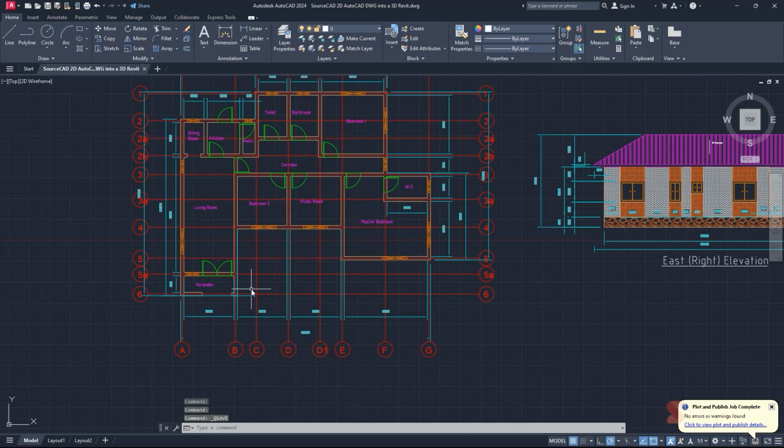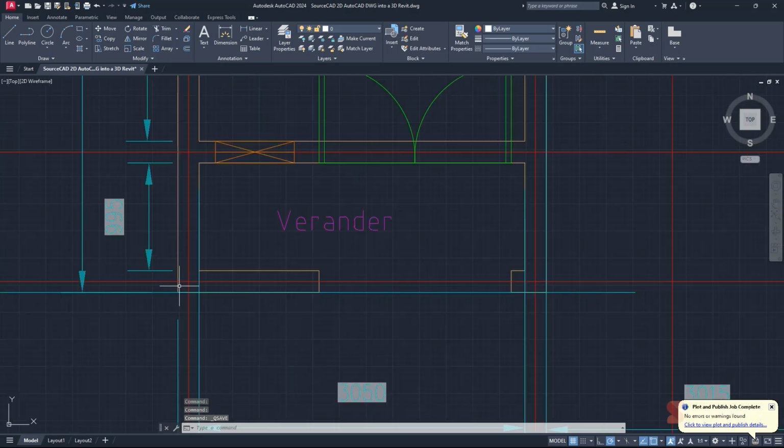After saving, we need to make sure we save or reselect our origin point so that it will become easier when we are working in Revit. And to select our origin is rather easy. Select on this Cartesian plane that we have on our bottom left hand corner. Hover your cursor over this square, then just simply go to move origin only. You can move origin and align. You can move the world or origin only. So for our case, we're just focusing on origin.